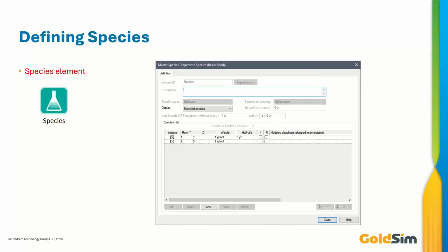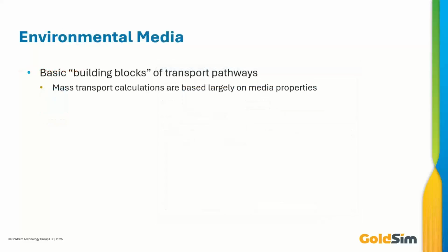But for most in the mining arena, you're just going to enter, these are the species I want to simulate. And GoldSim knows nothing about them. There's no database in GoldSim that knows the properties of iron. You're going to have to enter those properties, as you'll see.